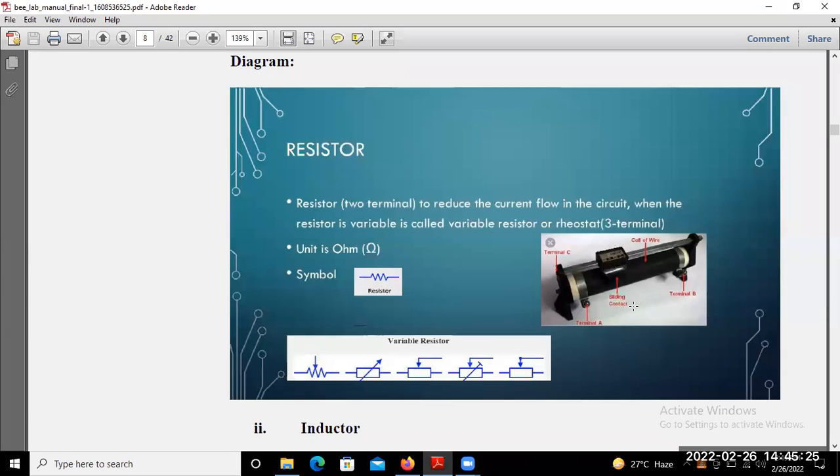If you want to connect a resistance at the maximum position and minimum position, how can you connect that? Suppose that this resistor has terminals A and B, and this one is your moving point, touching point. If you want this resistor at the maximum resistance value, at which point do we have to keep the slider, and for minimum resistance?